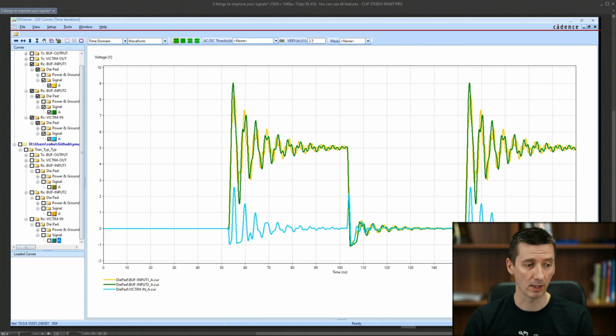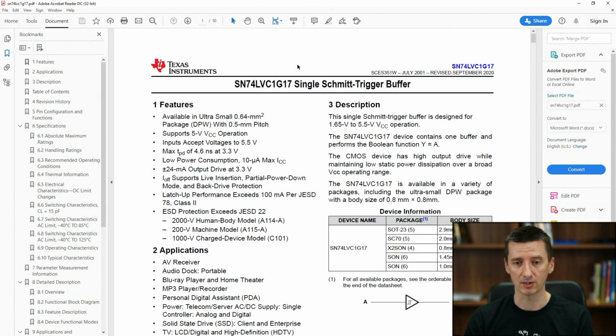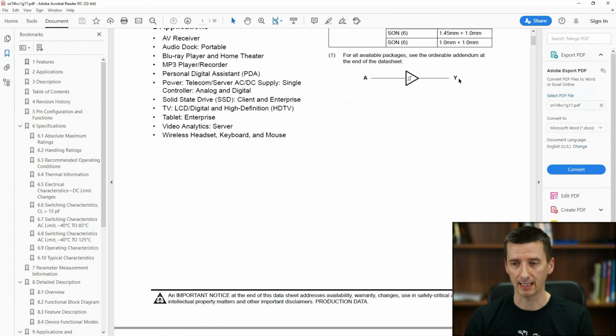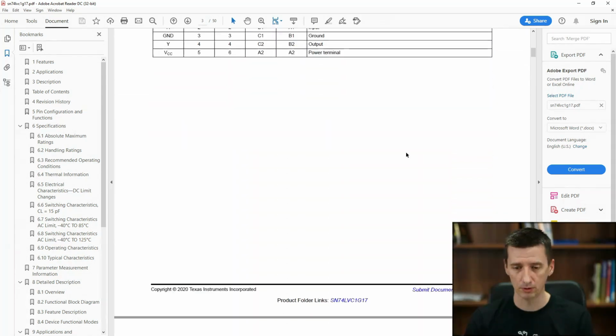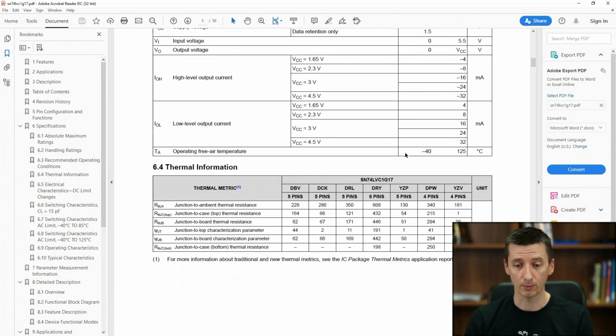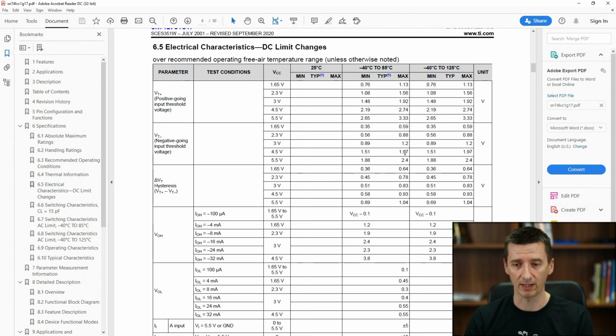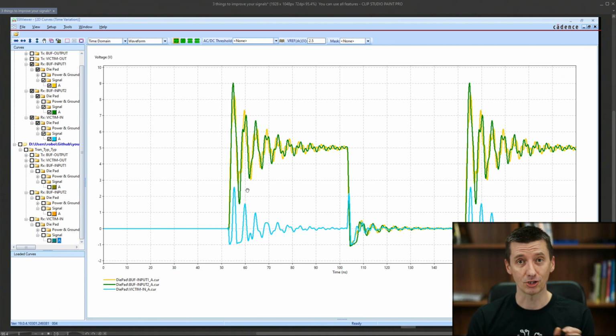If you have a look into the datasheet of this gate, and when you check the input levels for this buffer, you may find out that actually this high noise can change the levels of the output of the buffer. So we really don't want to have this kind of signals running through our PCB.